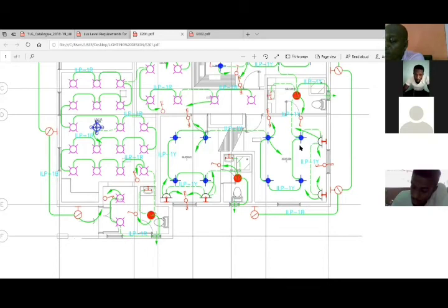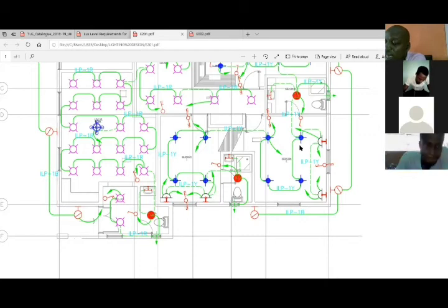Now that we have all that is required, can we substitute into our formula, the lighting point formula, which is equal to E times A all over lumen design multiplied by UF multiplied by MF. Our E is 200. Our area is 12, 4 by 3.